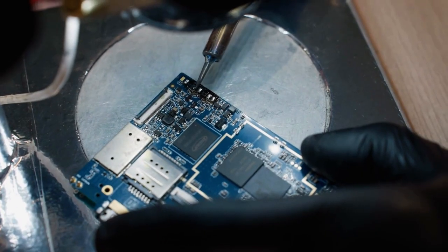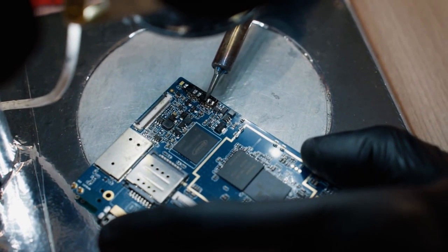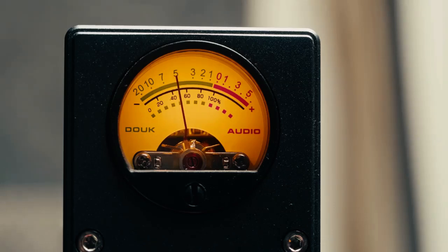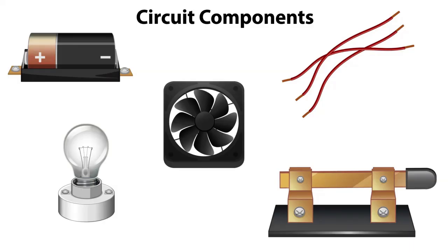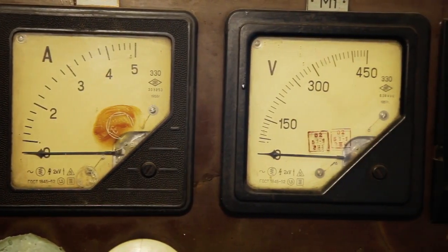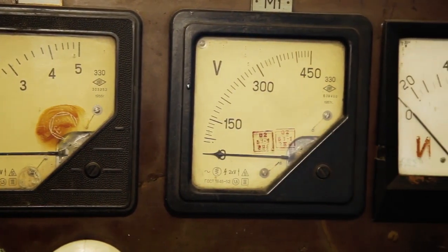When an input voltage is applied across the input resistor, a current flows into the inverting input node. Since the op-amp's input impedance is incredibly high, virtually no current flows into the op-amp's inverting terminal itself. Instead, because of the virtual ground, this input current has only one path. It must flow directly into the feedback capacitor. The capacitor then begins to charge or discharge based on the direction and magnitude of this current.